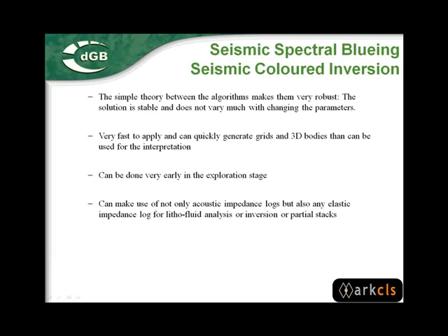In order to increase the frequency spectrum, I would think, yeah, there are some frequency filtering tools in OpendTect, but they are mainly tools to apply a low-pass, band-pass, or high-pass filter. I think Seismic Spectral Blueing is by far the most relevant one because it will reshape the input spectrum, whatever it is, to your well data. It is really the only technique that remains calibrated to your well data, and therefore I don't think any other, simpler frequency filtering tool could give better results.